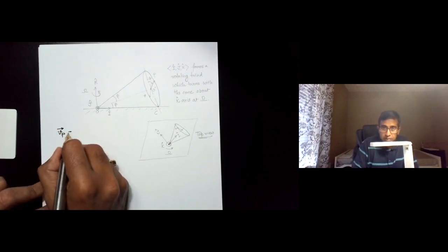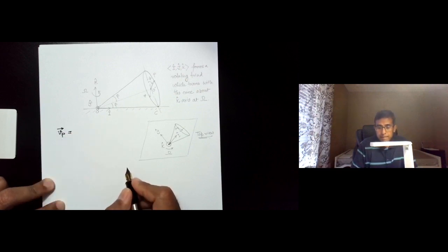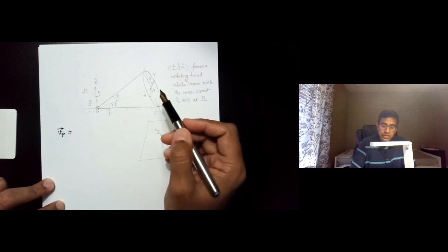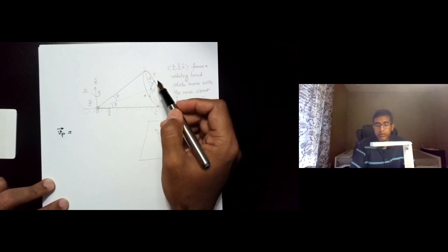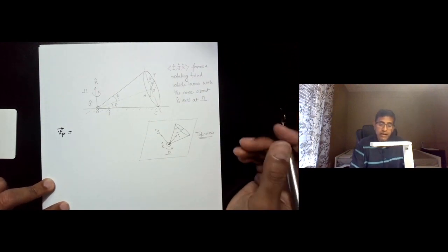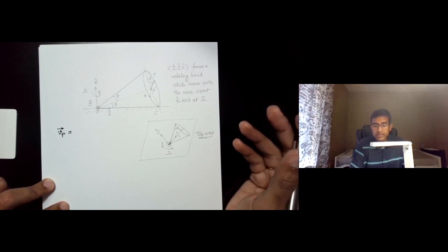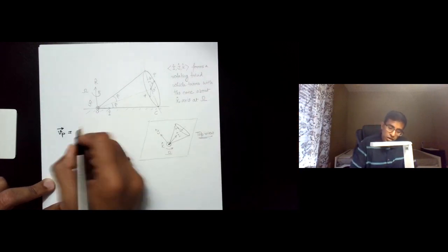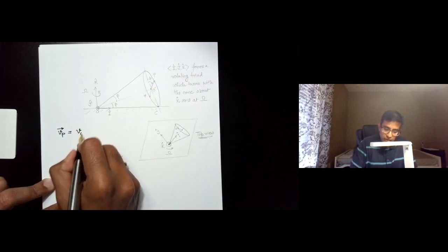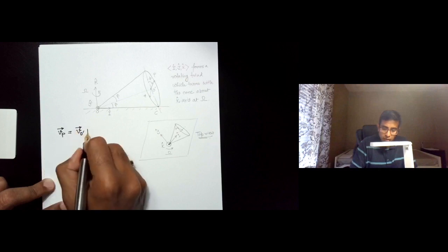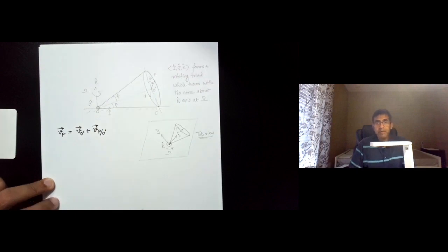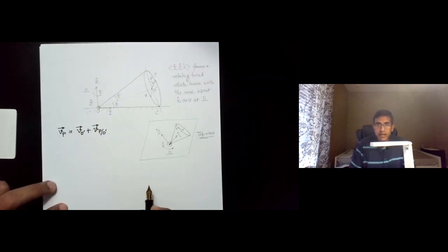If I'm interested in Vp, usually when you solve problems like this, you try to express the velocity of the point with respect to another point, and this other point is chosen where you feel that its velocity can be more easily determined. Okay, so I am going to express the velocity of P in terms of the velocity of O prime. So Vp is Vo prime plus the velocity of P with respect to O prime. Okay, this is the basic relative velocity equation.